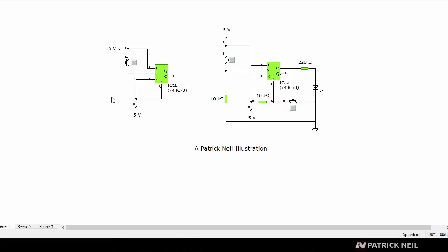And the reason for that is, if you have not noticed by now, the simulator will present a low signal on a pin if it's simply disconnected from positive power. So I do not need to physically put a ground to it. If I just leave the pin floating, it would be considered ground.